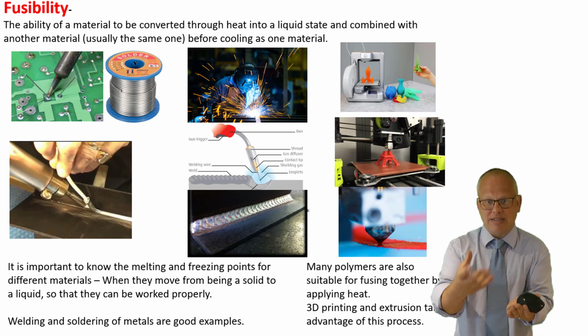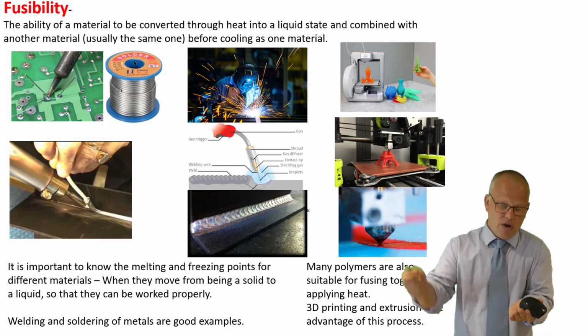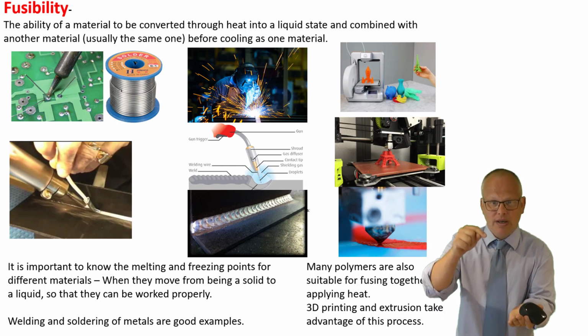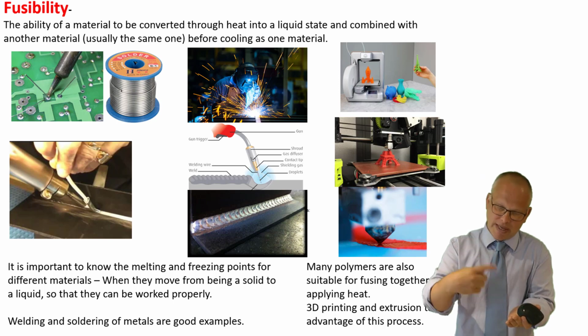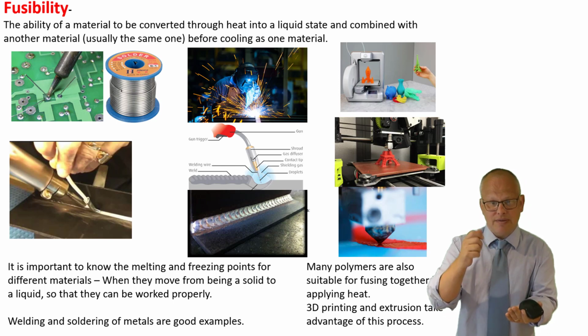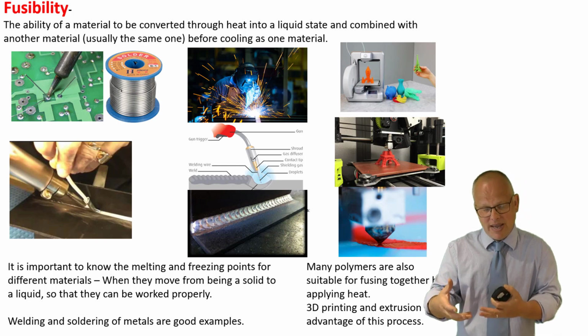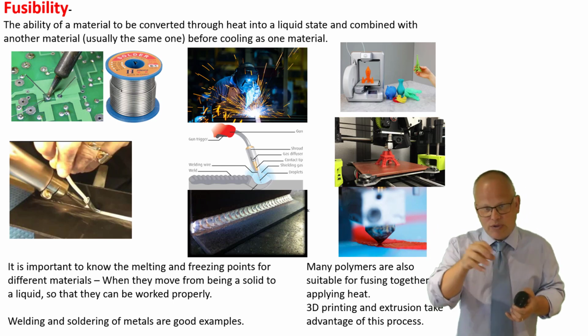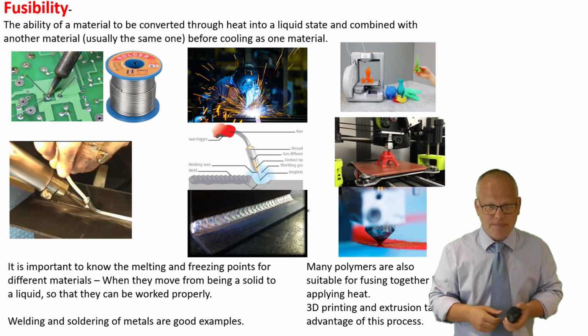Now, because a certain amount is lost along the way, or the shape's changed, a filler material is usually added, always really, in MIG welding, that's automatically fed into the weld pool. So you get that fused material, which should mean that if you were to X-ray it, there's no difference between the material on either side of the weld joint if it's been done properly.